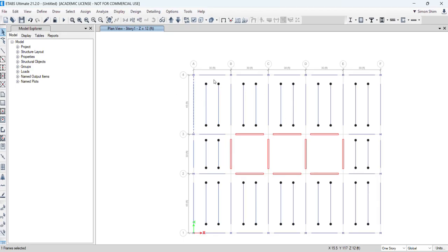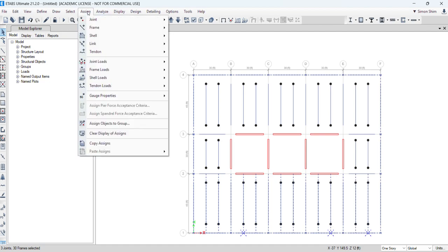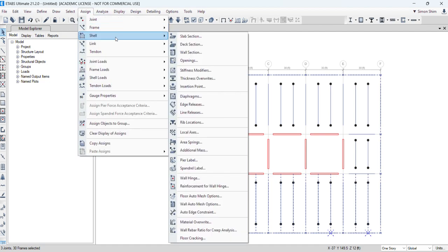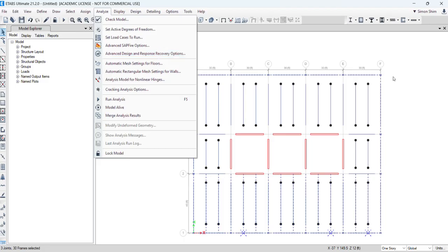The one thing that I want to make sure is we're going to learn composite beam floor framing. So for all even the girder, I'm going to release the moment so that we can design all the beams as composite action. So I select all the beams, which when I drew this, I didn't choose the pin moment release, so it doesn't have a moment release pin connection.